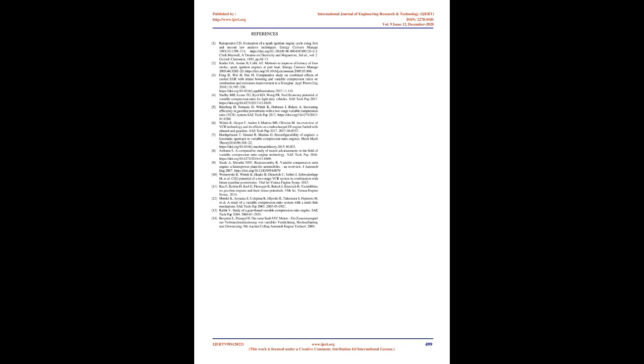In this section there are no changes in its opening and shutting valve. It is designed to simply open and close with simple rocker arm arrangements according to the size of the engine. Electro-mechanical arrangement, air intake valve. In this section 2 types of arrangements are there just to increase or decrease the compression ratio inside the combustion chamber. This dual cam profile for the air intake manifold is arranged in such a way that we can easily switch from one profile to another by just energizing the electrically controlled valve with the press of a button.